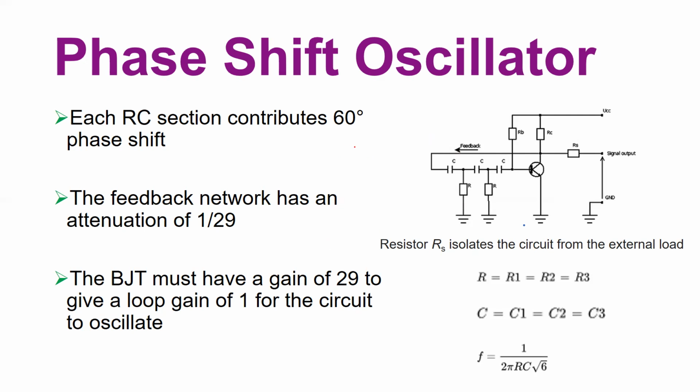So if you recall, we basically have this gain block here, and we have this feedback network. We will say that this gain block has open loop gain AOL, and the feedback network has a gain of beta, and you have an input to this network, and then you have the output of this network. So this is basically an open loop system at the top.